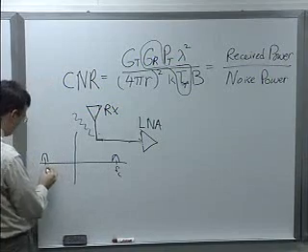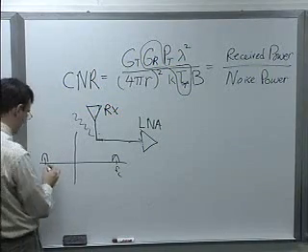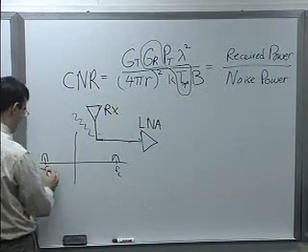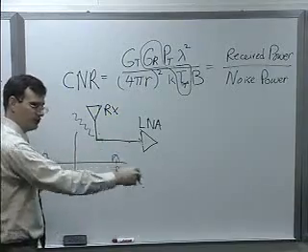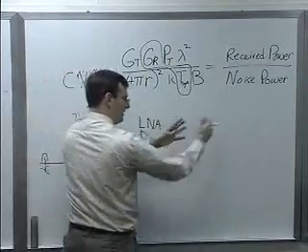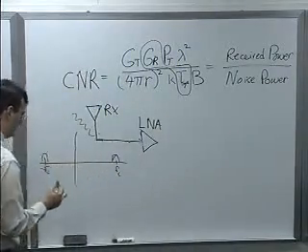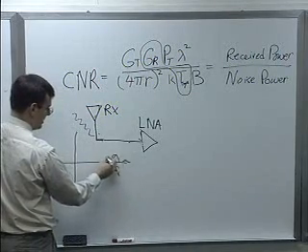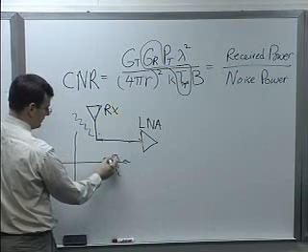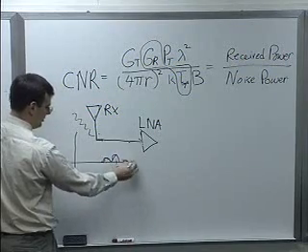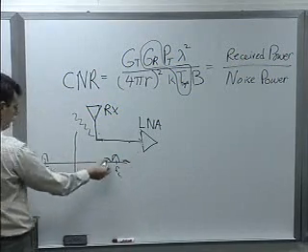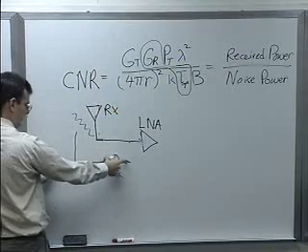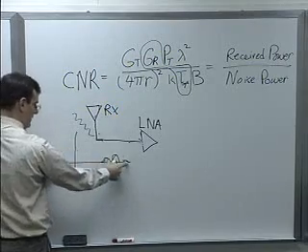And remember, it's like the fourth day of class, we talked about a transponder and how you mix signals down. And we're going to eventually want to do that here in our receiver chain. So if you have some harmonic content up here, and when you go to mix it down, you basically multiply it by cosine that shifts it down.